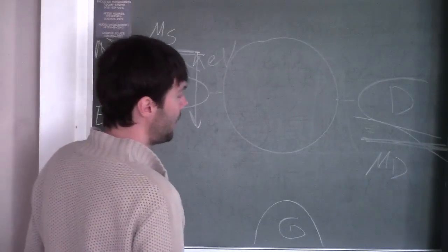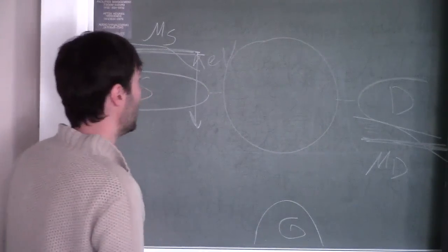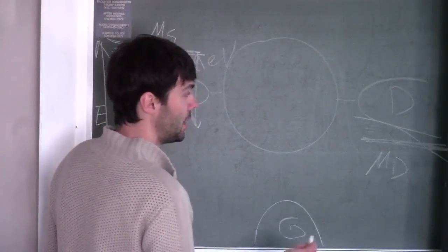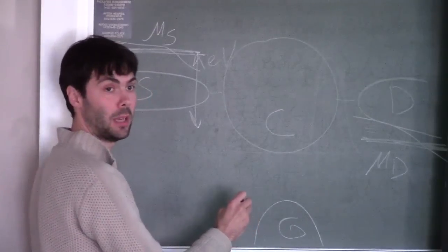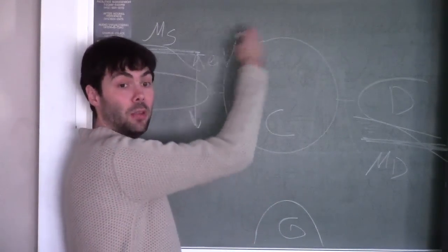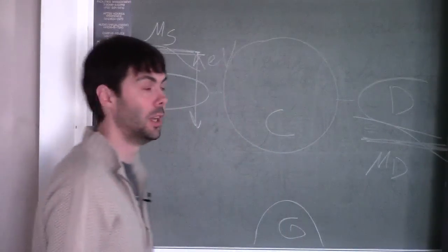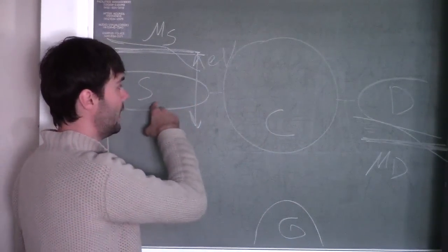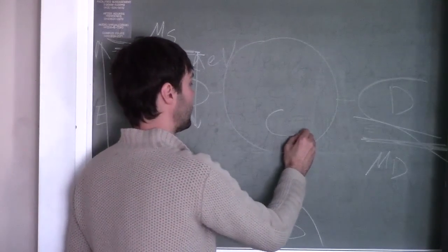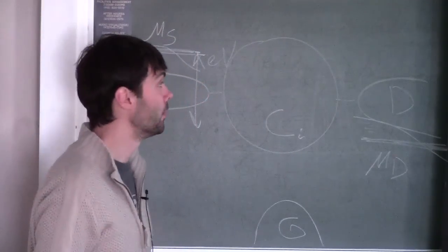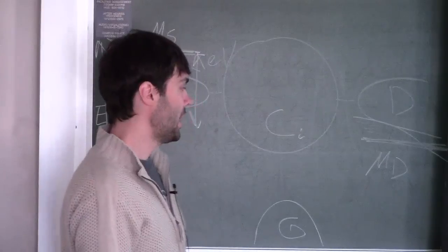Now, we have to go onto the island for talking about all the rest of these. So first of all, a charging energy: well, this island would have some capacitance, and this capacitance will be its self-capacitance, and that's what's calculated here. But it will be influenced by the nearby source, drain, and the gate. So it will be some capacitance of the island, and that would give me this energy scale.